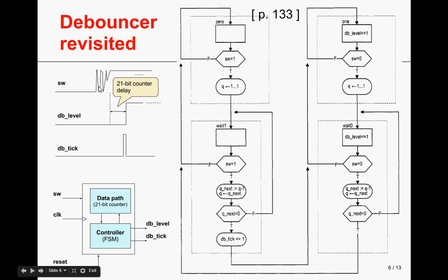So whenever we read a 0, because of a glitch, the state reverts to 0. Now, if we don't read a 0, then we will order the counter to decrement by 1 unit and then check if it has reached 0, otherwise we will continue to do this test.